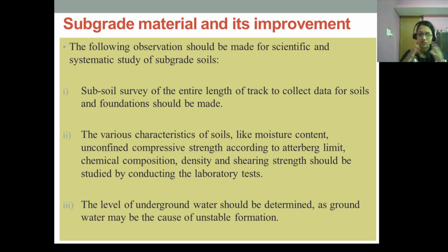Proper drainage also improves the subgrade. The best choice of material for embankment should be dense, free from excessive moisture, high in internal friction and cohesion, possessing low compressibility and low capillarity. Soils which are low in internal friction and cohesion tend to flow or spread out, especially when there is excessive moisture. If highly compressible, the bank continues to settle down under traffic. Low capillarity tends to keep the formation free from excessive moisture.